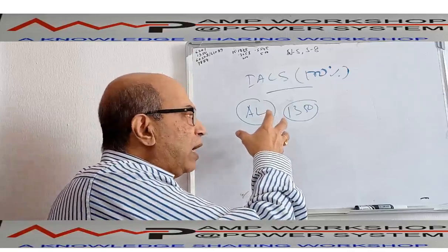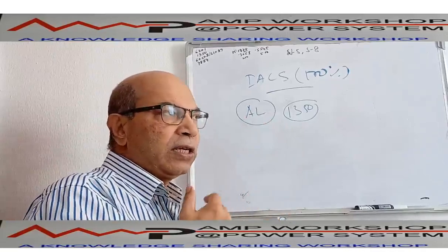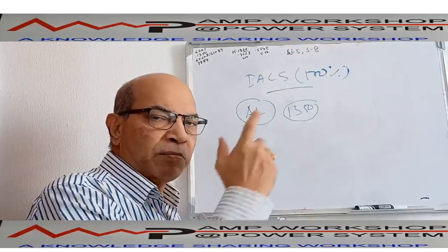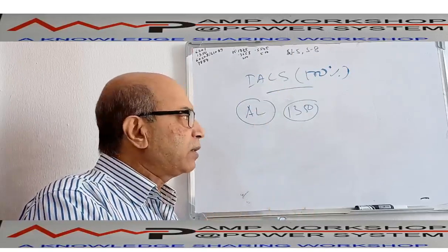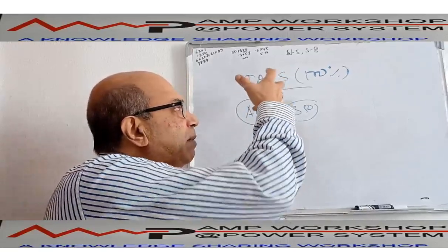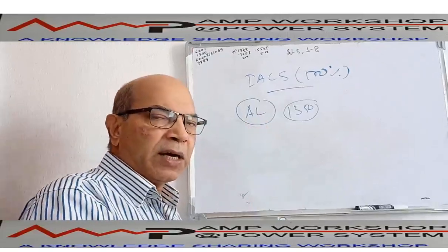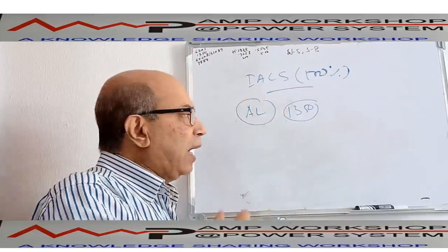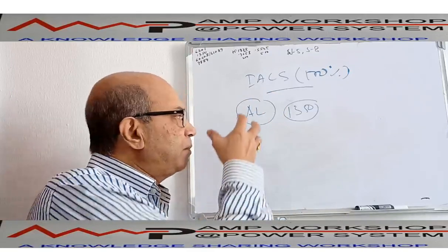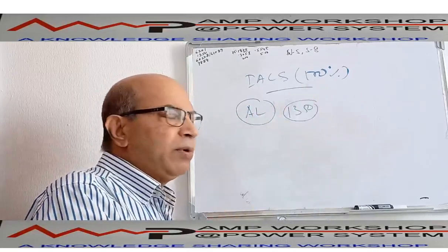Now, the specific gravity of aluminium is very low in comparison to copper. So you can string the conductor over a long distance between the two towers. You can make the distance between the towers long. Aluminium has about 50% of the mechanical strength of copper. And as the specific gravity is low, as I have already said, you can span a long distance with aluminium.